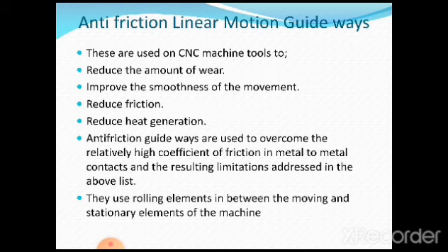So now let us understand, related to the previous presentation slide, the necessity or advantages of using the anti-friction linear motion guideways. All these things we already discussed, just as a revision, and very important to note here is to reduce the frictional resistance between the moving elements. Whenever movement takes place between two parts, we require to reduce the resistance to friction. If frictional resistance is reduced, then it is possible to reduce the heat, and also there is not much lubrication required. So many factors can be